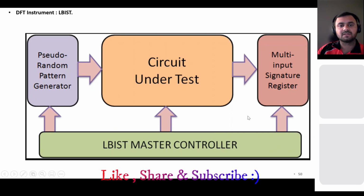The controller generates the control signal for the circuit under test, and then you have your ATPG patterns. Based on the control signal and patterns, it tests the internal logic and compares with the stored signature. If the comparison matches, it signals a pass. If it is not matching, it is a fail. Then you need to dump the waveform and see why it is failing.